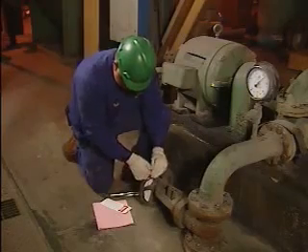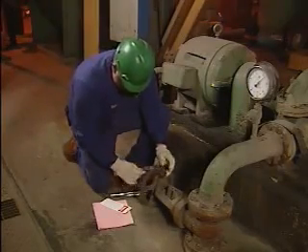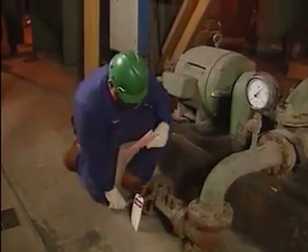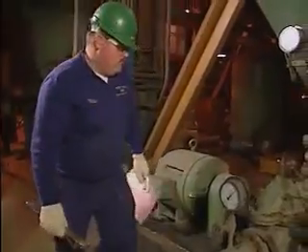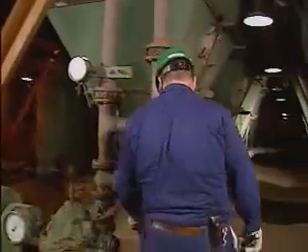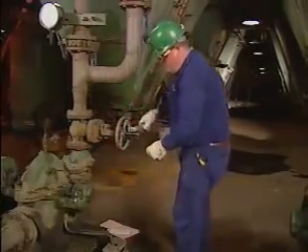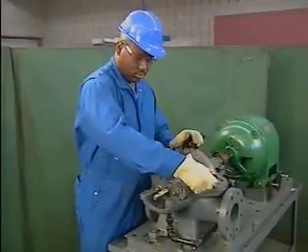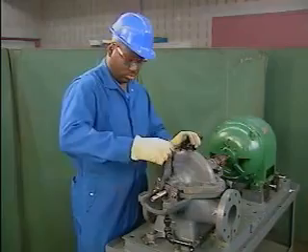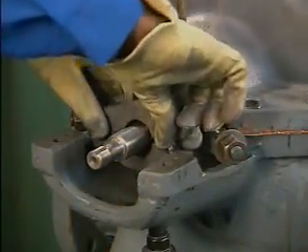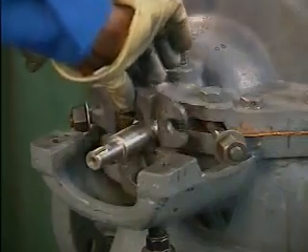To show one way of removing packing, we'll use a pump that's been removed from the plant for service. Following company procedures, valves were closed, locked, and tagged out to isolate the pump before it was removed from the system. The pump was also vented and drained. The mechanic's first step is to remove the nuts that hold the gland follower in place. This pump has a two-piece gland follower that allows it to be removed from the shaft.